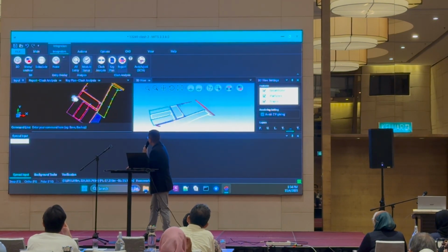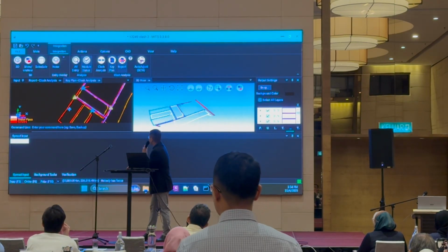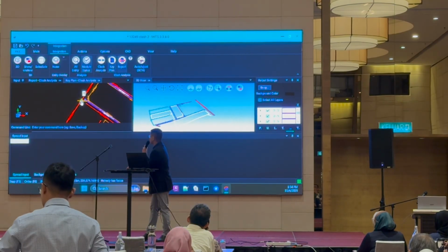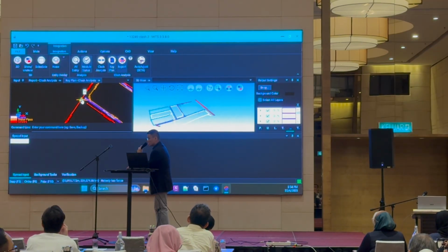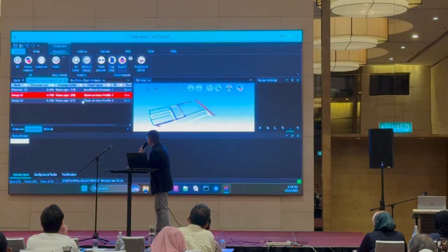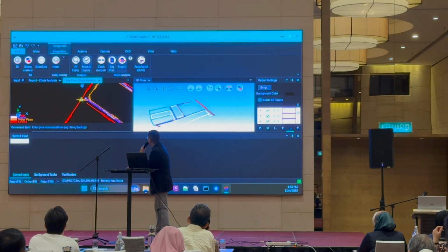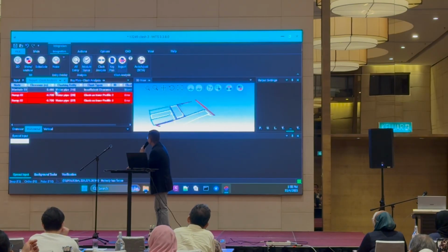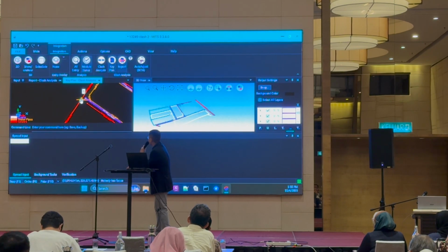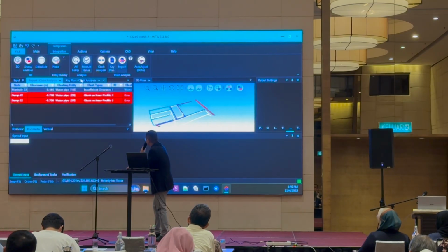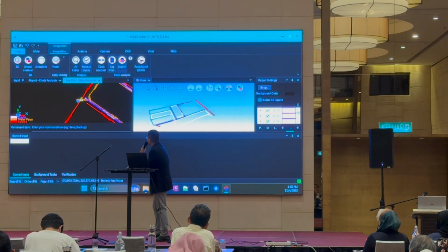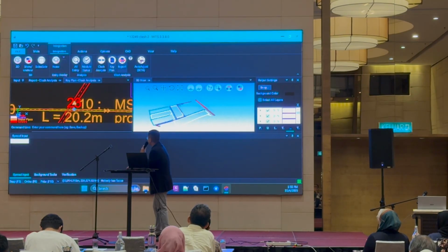Now, if you are inside this clash analysis, it will tell you what is going on here. We have a warning sign. You can click on the warning sign, and it brings you to exactly what is wrong. As you can see when you click, it is ID number one. This one has a clearance of 0.486, which is apparently not sufficient according to this software. So we can check whether this 0.486 is really consistent or not.